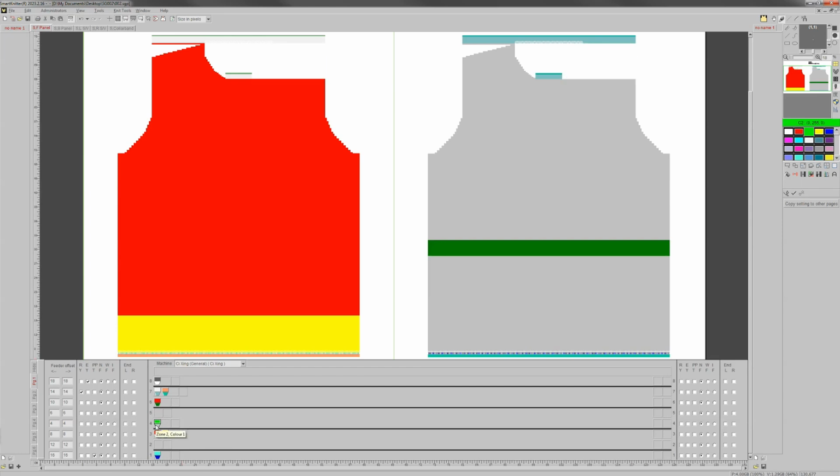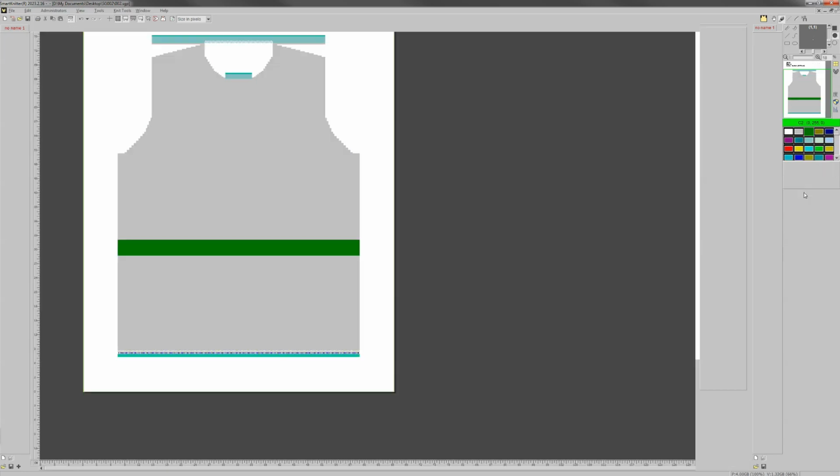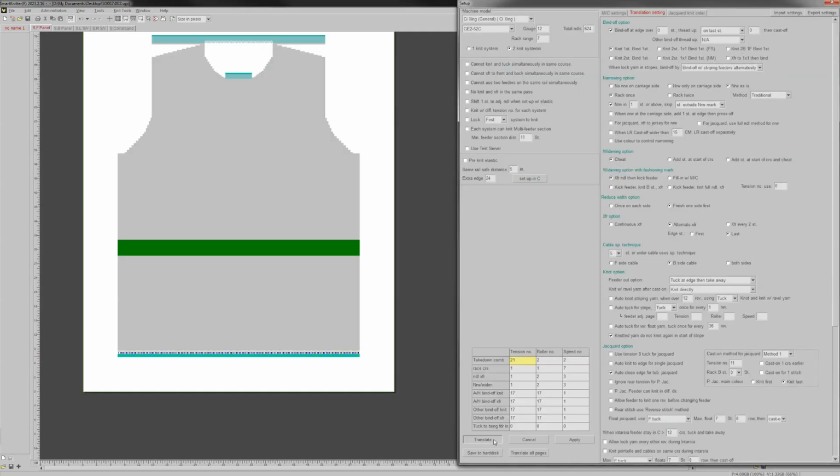There are extra properties we can set for each feeder. Right-click on the feeder to select the appropriate type. Feeder 4 is for knitting the right shoulder of the front panel using partial knitting. It is marked as Zone 2, green, and color gray. Select Partial Knit Feeder for Feeder 4. Note that there is a black outline around the feeder icon.